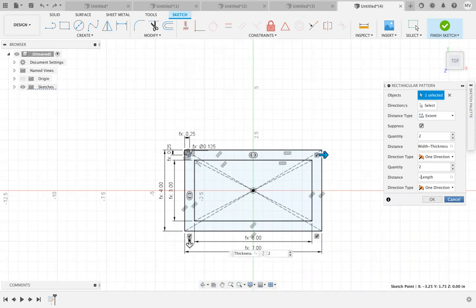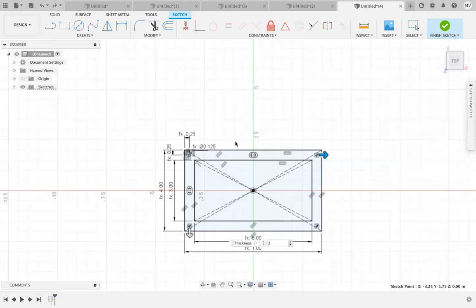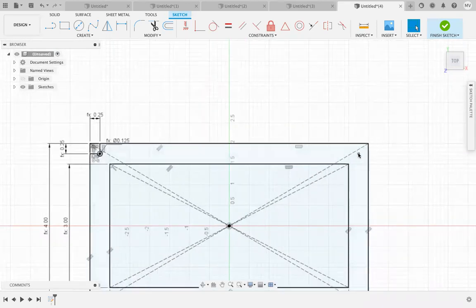But I'm past the bottom edge. So we want it to go down length, and then we want to go backwards thickness. So it should be minus length minus thickness? No, why not? Because minus is moving farther down. So actually it's negative length plus thickness. There we go. I hit enter. My holes are all in the right place on the middle of every side.